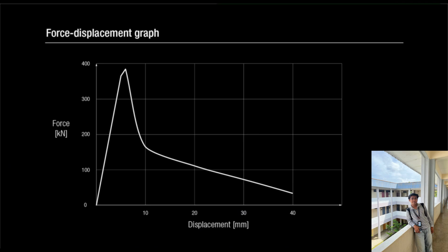When wood is stressed in compression perpendicular to the grain, the hollow cellulose cells don't offer much resistance to crushing, and the behavior is highly nonlinear. The strength perpendicular to grain is difficult to measure precisely, given the concentrated stress-strain behavior of softwood under severe loading deformation. Wood under severe loading deformation compresses to about 1/3 of its original size.